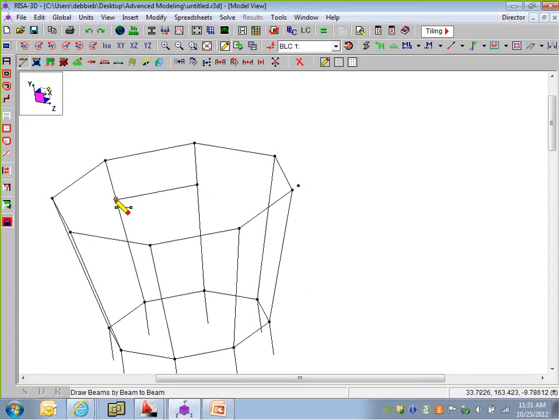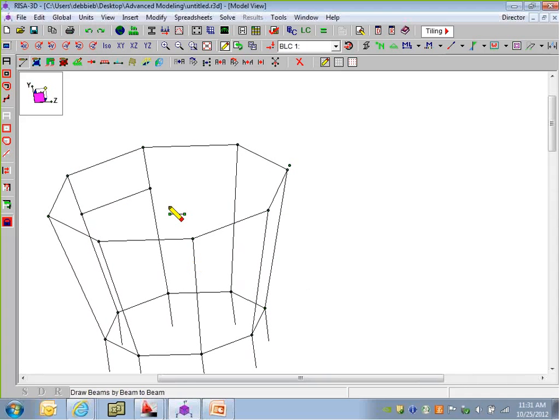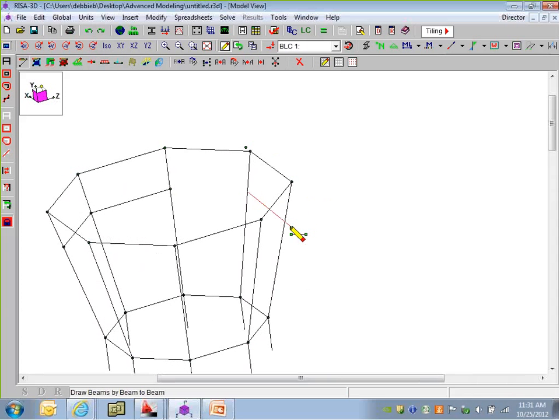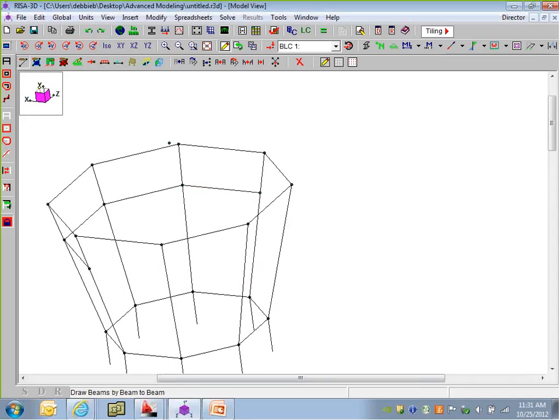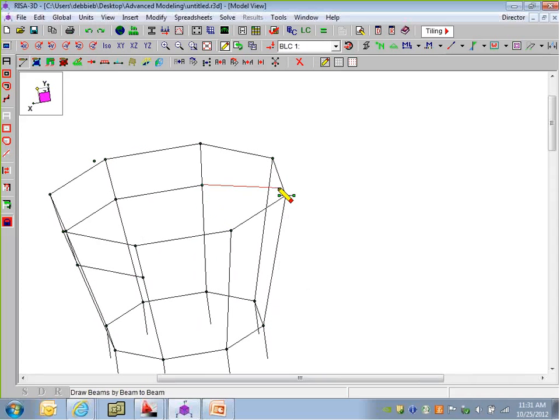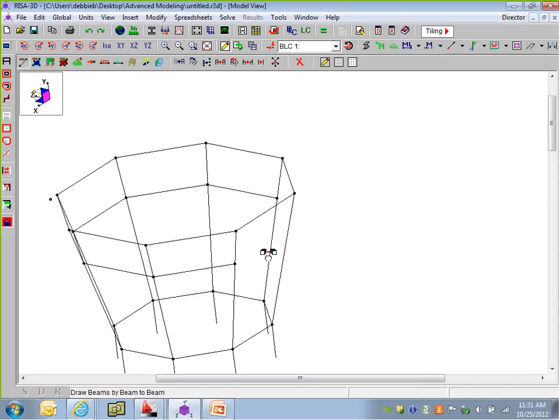Now, that's not exactly 15 feet because we're looking at a diagonal. So it's 15 feet around the rake, which is nice. It actually calculated that exactly along the rake. So let's click on here, and I'm just going to go around there. So there's some tools. Those offset tools are really great ways to calculate exactly a member-to-member offset.